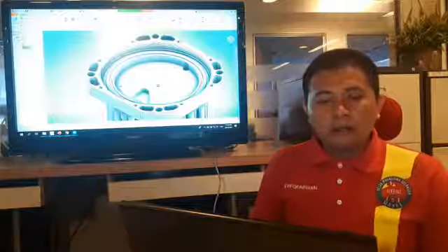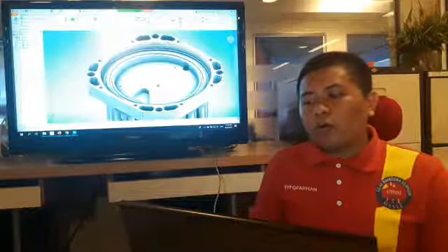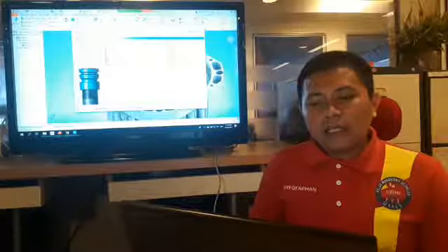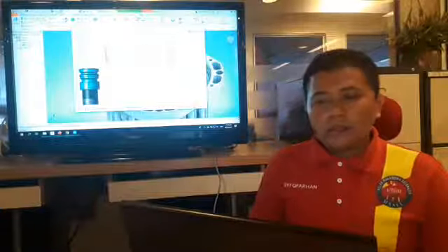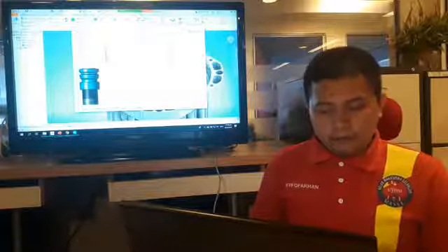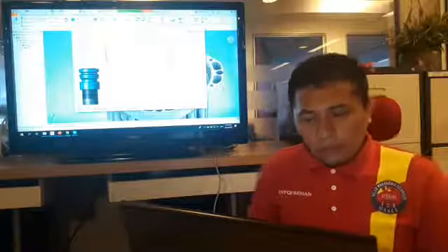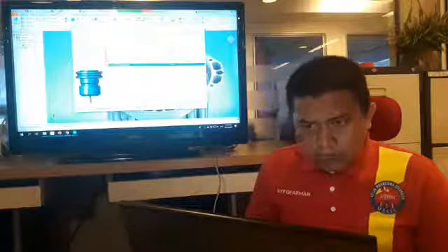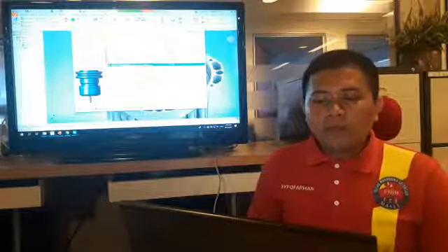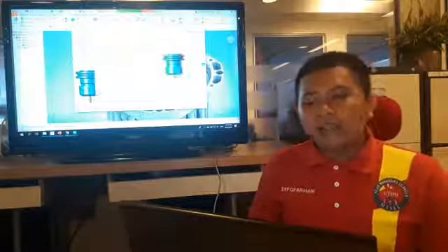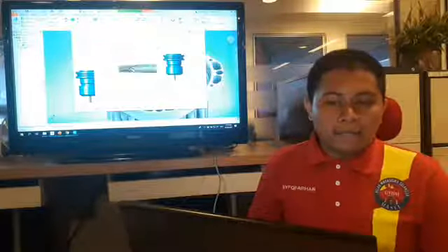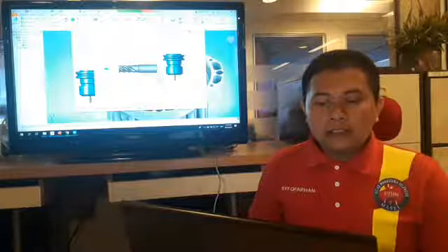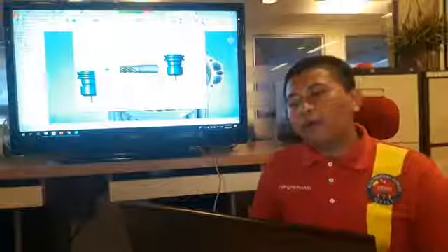For example, you go back into your tool libraries, inside the document for these tools, so you go back into your flat. So just simply edit these things. Okay, go into the cutter tab, so you can change the overall length of your tools.